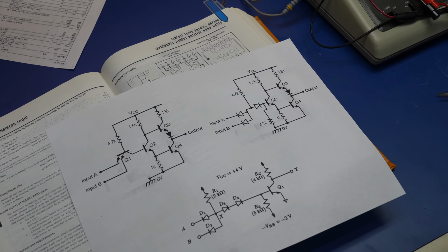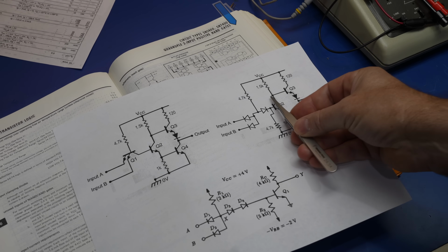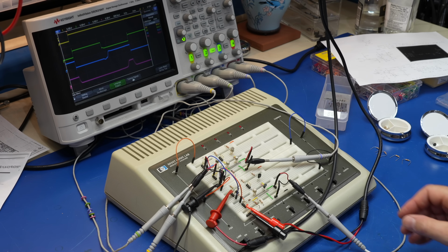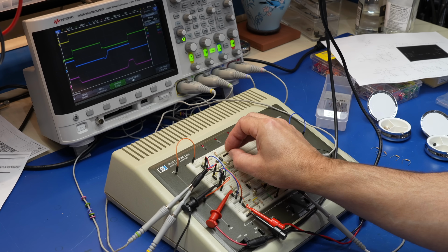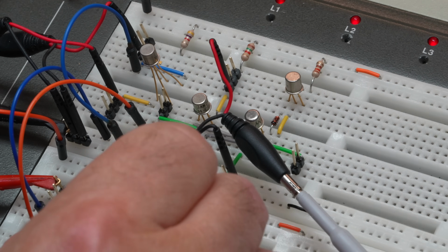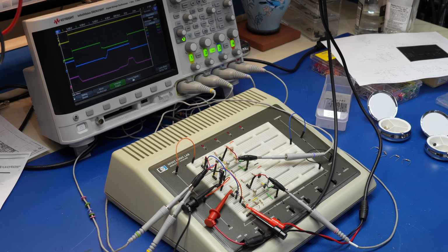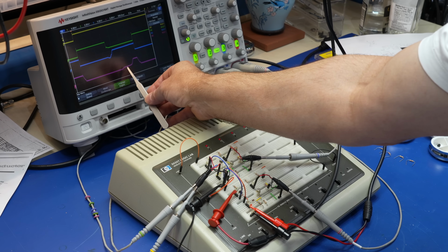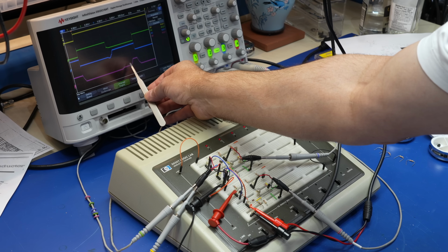I say, well, let's go back and see where the delay appears. So I'm going to go from here to monitoring here and see if this stage introduces a delay. On my breadboard, I have to move this to the collector of Q2, and I'll do the same on the DTL gate. Alright. And here we start to see some interesting component to the delay. It doesn't go up right away, it stays down and then goes up. So it goes to an intermediate level.